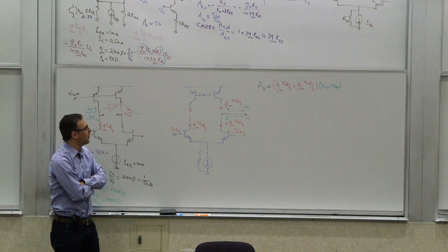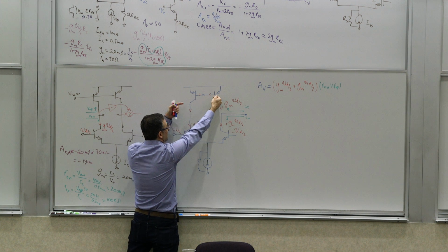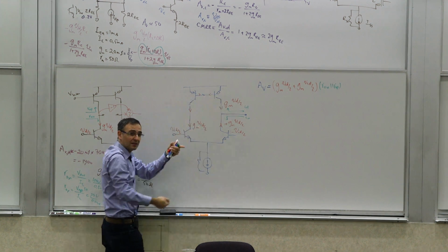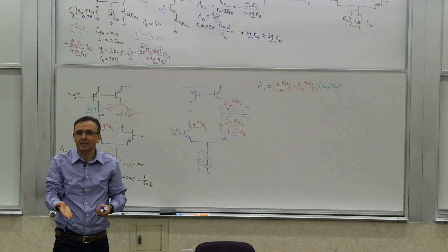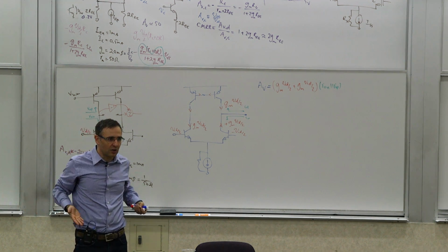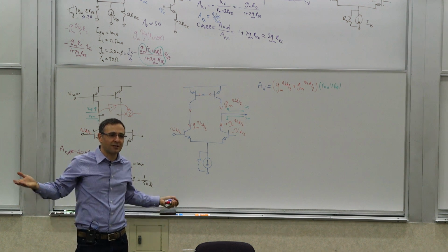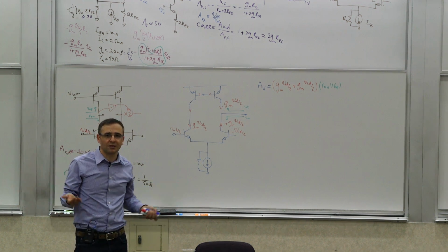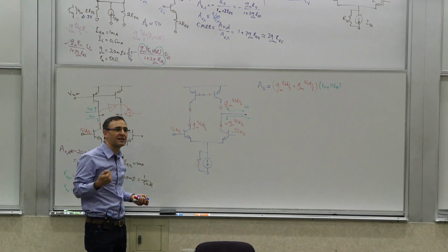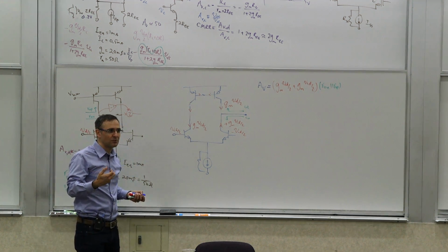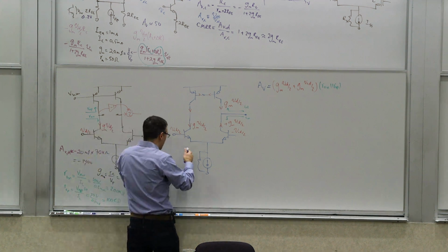Yeah, it's kind of floating in the sense that it's not connected to anything. But these base currents, for PNP, are coming out, right? You have two things that need to provide DC current. Yes, small, but still DC current that needs to go somewhere. If you just leave it open, this will accumulate. It will just go to a voltage and it will saturate and nothing will happen. So there needs to be a pathway for this current to be drained out. It needs to be shunted out, right? So that pathway is placed here.